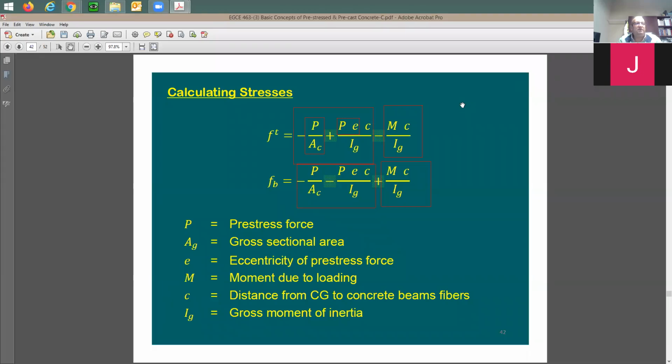So what happened, I started here by discussing the general equation for stresses top and bottom for any pre-stressing case. This component, the first term, which is this big box, you have here two terms inside it, right? This is going to be for the pre-stressing force. For the top, you're going to have this P for the axial. This is going to be the pre-stressing force, and this also the pre-stressing force. So these two little components, which is this big component, this is for the pre-stressing force.